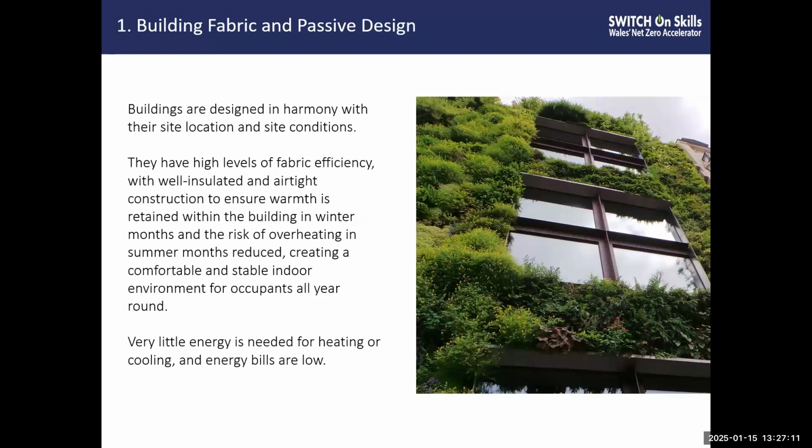So let's go on to some of these principles now in a little bit more detail. Firstly, buildings should be designed in harmony with their site location and site conditions. They should have a high level of fabric efficiency, well insulated materials, and well insulated airtight construction as well, to ensure that the heat and the warmth that we're putting into the building stays and builds up, especially during the colder months.